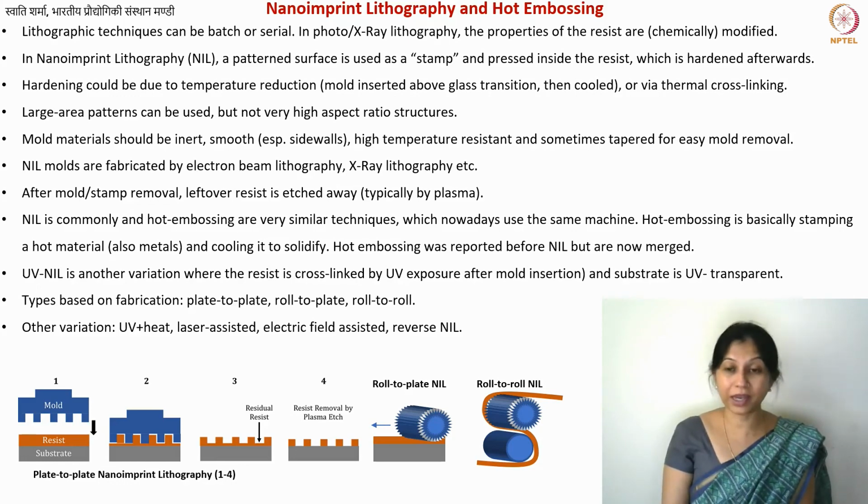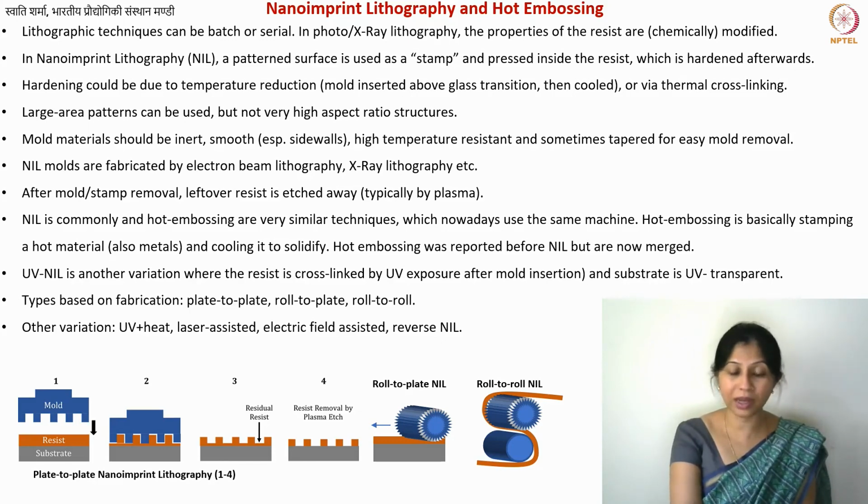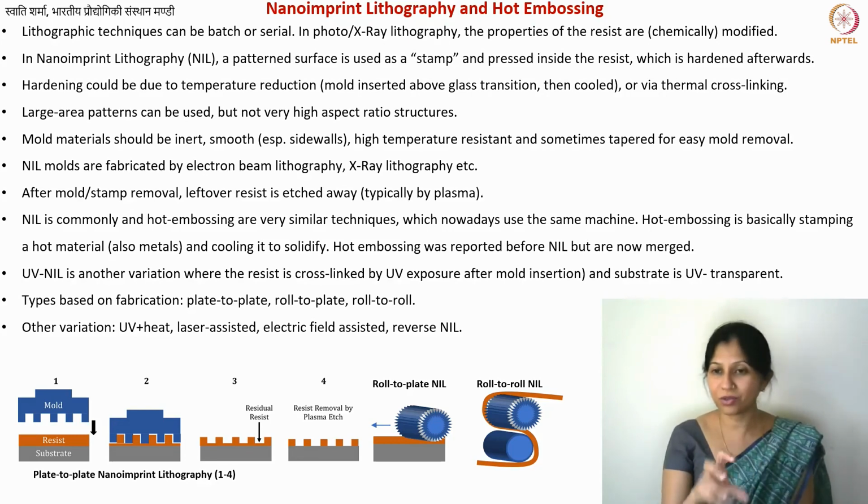Also, glassy carbon is mechanically much stronger compared to the polymer. It has an inert surface, so polymers may degrade or corrode over time, but that does not happen. You know how stable our glassy carbon is. All of these properties which I had discussed with you for the large scale structures, when we were thinking about making vessel liners using glass-like carbon, or large scale electrodes, are also true for nanoscale or microscale glass-like carbon. That is why, immediately after you convert these structures into carbon, you can have many other applications which were not possible using the polymers.